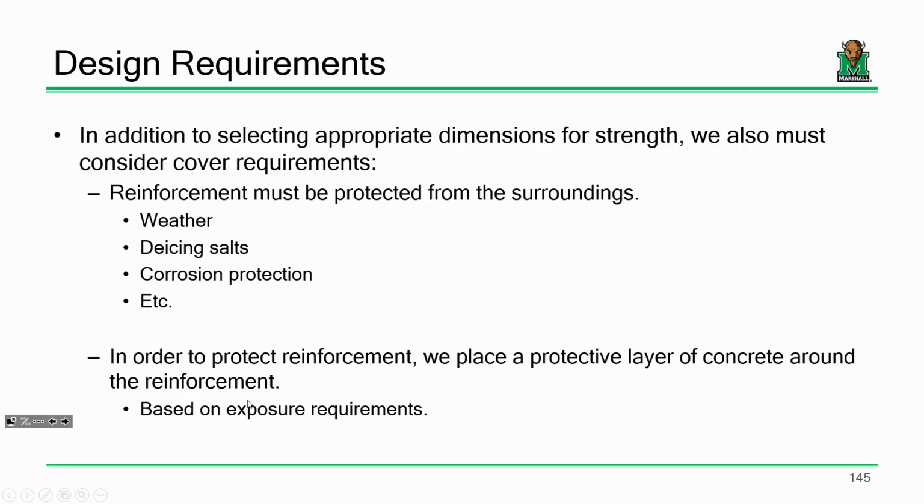There's this concept in reinforced concrete design called cover. Cover is a dimension that defines the distance between the face of the rebar and the face of the concrete. More cover is required for different conditions. To give you an idea, if I'm talking about the interior column in a building, I might require 1.5 inches of cover. In other words, there's got to be at least 1.5 inches of concrete around that rebar to protect it from the weather and corrosion and things like that.